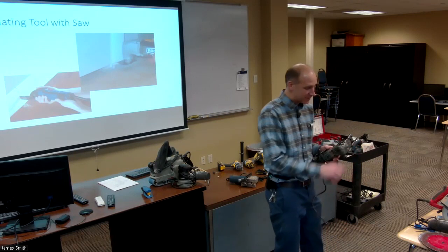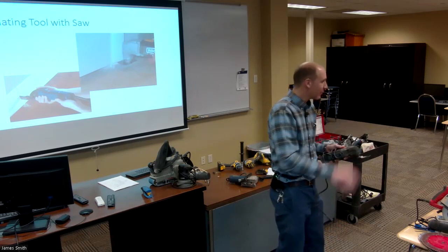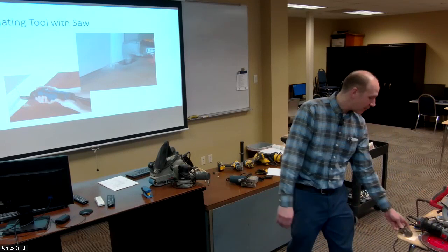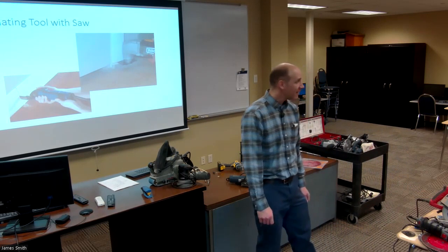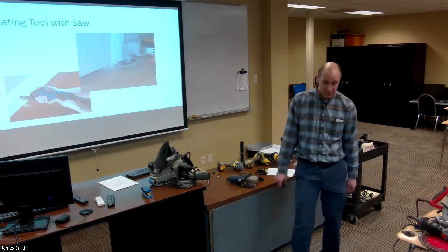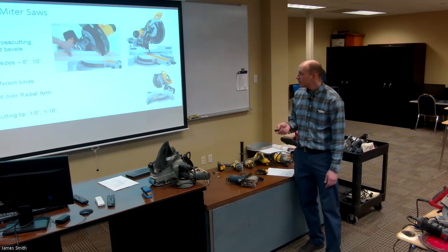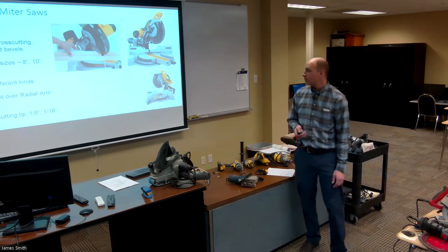I find that when the teeth get dull, obviously it doesn't cut as well, but you can still remove material and it just kind of burns right through the material. It works. You've got to be careful not to hit any nails because those little blades, they're not carbide. The challenge is when you're trying to cut so close to the floor, you just don't have a lot of clearance. So that is really the best tool I've found to do that. There is a picture of it right there. So that's called an oscillating tool, multi-tool.